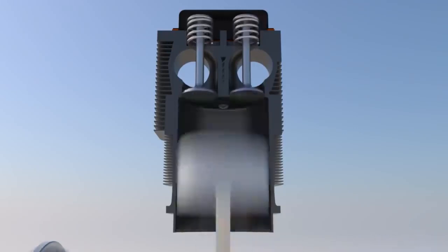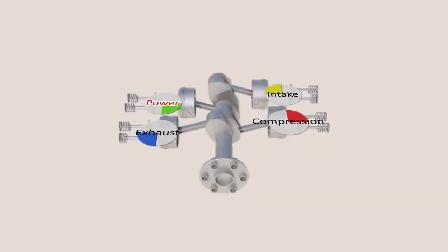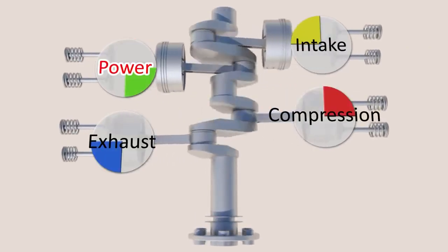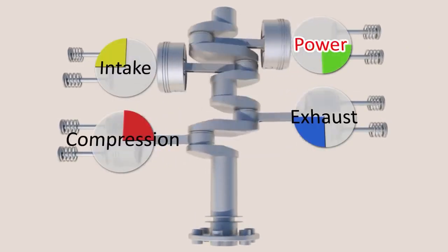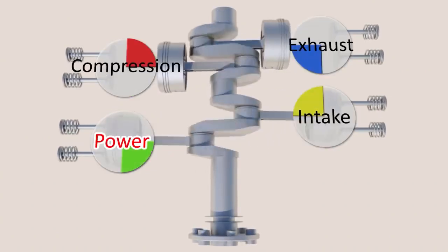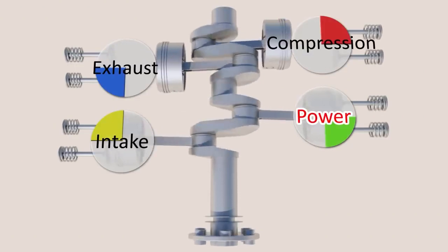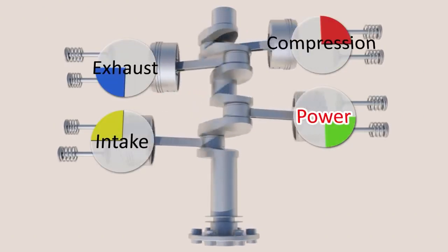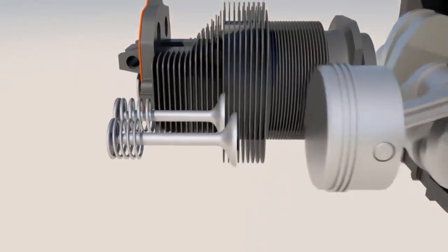On a typical four-cylinder engine, each one of the cylinders is in the middle of a different stroke. That way one cylinder is always in the power stroke and the engine is able to keep the crankshaft rotating, thereby allowing the remaining cylinders to go through their respective stroke. As we just saw in these four strokes, there are two valves at the head of each cylinder that open and close to allow the fuel mixture in and the exhaust gases out.